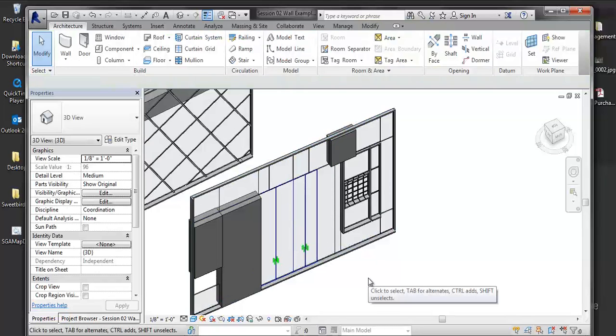So if I'm doing layouts on a building skin, and I know that I'm going to have irregular divisions, instead of trying to go in and tab through and grab the curtain grid line every time, I'm going to make a series of reference planes and align and lock them so I can push and pull dimensions that way a lot quicker. And that kind of leads into building families and so on.